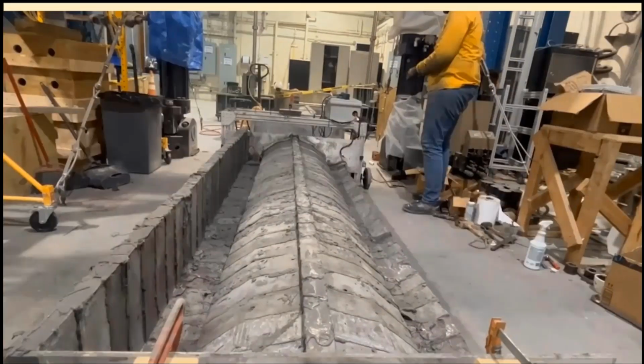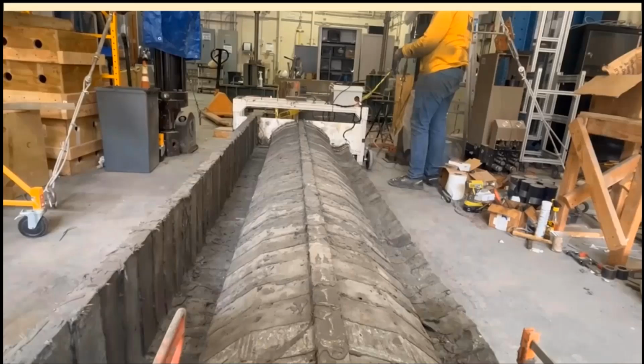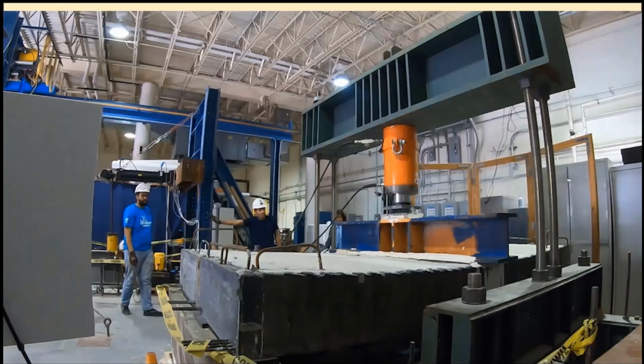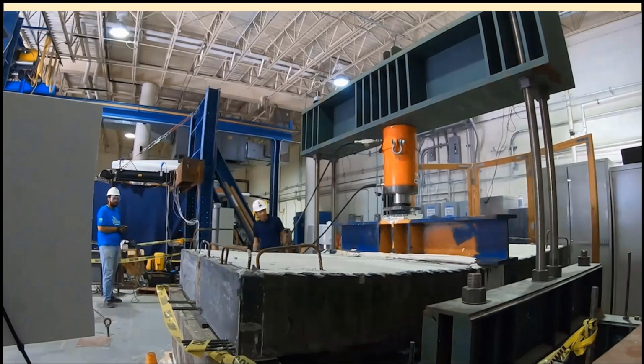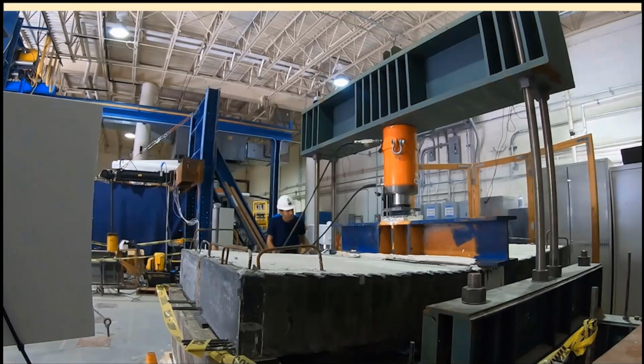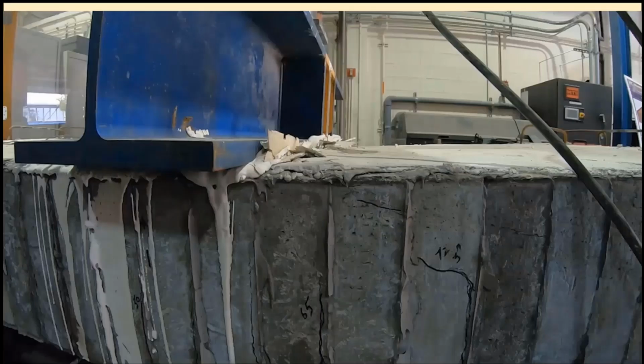I believe this one was around 20 feet or so. After that, we put the reinforcement in, filled it with the concrete, and then did the flexural test. Even in this case, the shell showed a localization of the cracking, and then one crack dominated. It showed a fairly nice behavior and capacity.